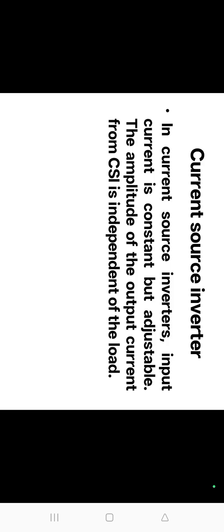The source current I1 now flows through IGBT T1, the parallel combination of R and C, and then through IGBT T2. From 0 to t2, IT1 is equal to IT2 equal to I. Output current I_AC is minus I. Capacitor voltage Vc changes from minus V1 to plus V1 through the charging current IC. Hence, load voltage VL is equal to Vc. Thus, the waveform IL is equal to VL by R, Vc by R, and has the same nature as Vc.